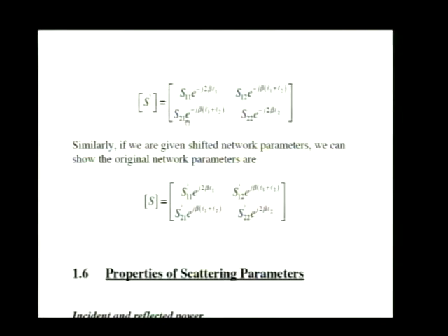This isn't the equation that's most important. The equation that's usually used in practice is to get the scattering parameters of the amplifier in terms of the scattering parameters that you measured for the amp plus transmission lines. The only difference is that those scattering parameters have extra phase terms added into them that you've got to get rid of. Phase terms due to the fact that the signals coming out of the amp travel down the transmission lines from each side, picking up phase delay as they travel. So you simply get rid of those added phase terms by multiplying by appropriate factors, and here they are, in terms of L1 and L2, the lengths of the two lines connected up to the terminals of the amp, and beta, the phase constant, 2 pi over lambda for the transmission lines.